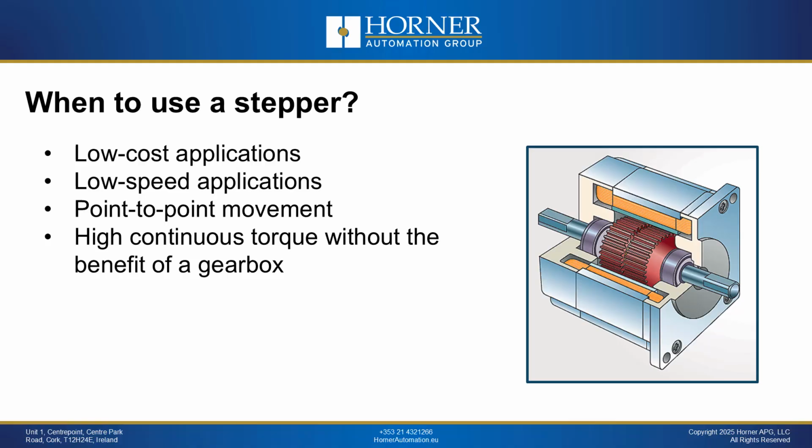Now, when would you use a stepper? Low cost applications, low speed applications, where you are moving from one point to another, maybe going from point A to point B to point C and back to point A. You get high continuous torque without the need of a gearbox.